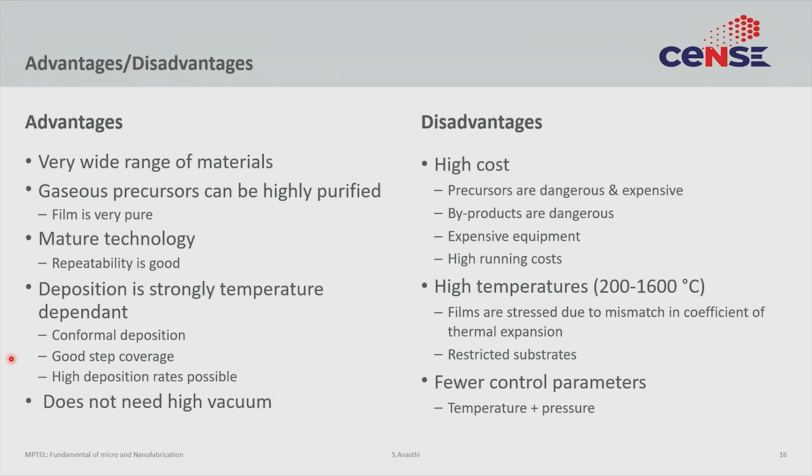The other extreme would be, say, physical vapor deposition, where in sputtering you have access to bias voltages, you have access to temperature, you have access to pressure, you have access to stoichiometry, you have access to different types of targets, etc. So, in that way CVD is a little restrictive. Of course, the flip side of that is it's relatively easy to control and it's repeatable, while some of the PVD processes tend not to be.